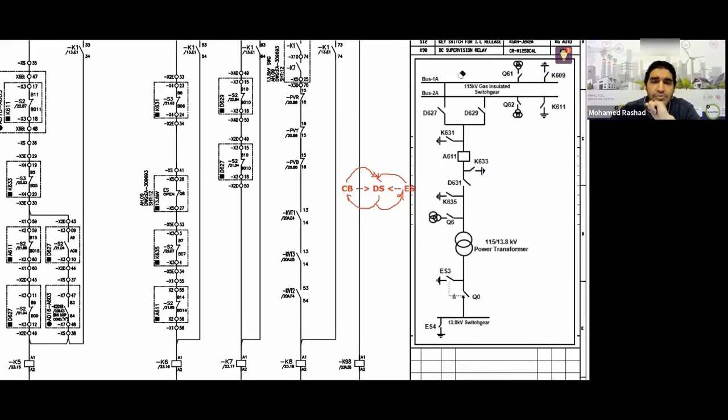Okay, I came and told you what? I told you, suppose with me that this disconnector is closed and this breaker is closed and this disconnector is closed and you were feeding this transformer and this transformer was actually working. And for some reason, you now want to take out the bus that is underneath, you want to take it out for maintenance, or there is a problem with this bus or something. And what do you want to do? You want to transfer your load to the upper one. Is there a question?